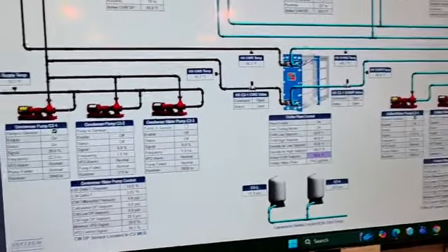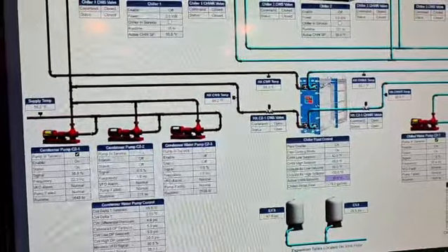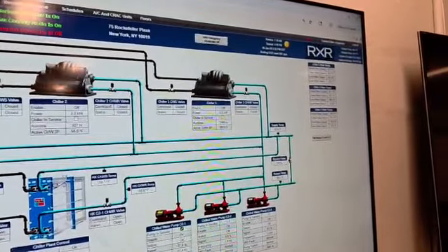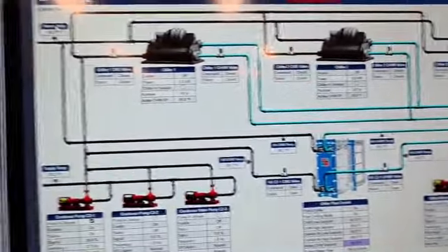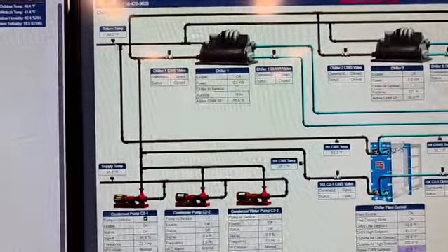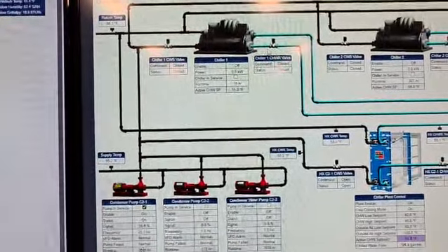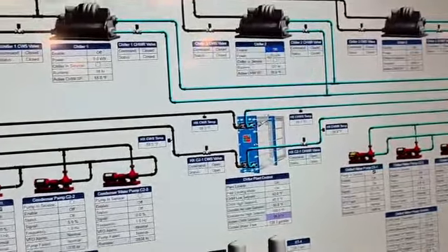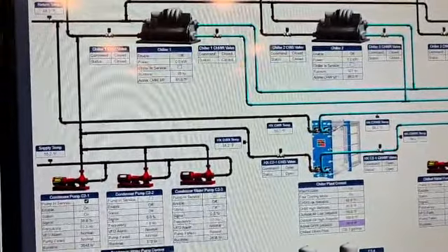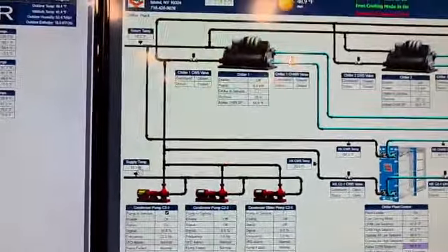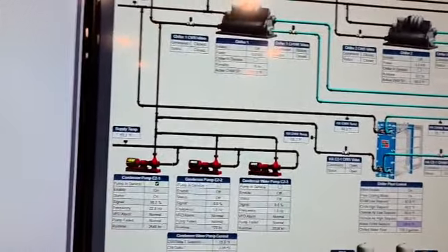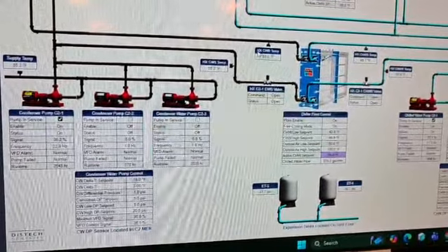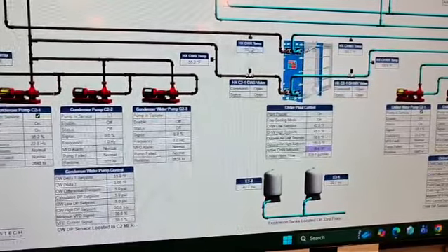Now you have this thing in here, which is called free cooling, right? That's during this time when you're between seasons. Sometimes the cooling tower cools the water cold enough that you could cool your building with the water without using the compressors. You see the compressors now are off. You don't need them because the cooling tower water is cold enough to cool the building. So what you do is use this device, which is called a heat exchanger, the HX.